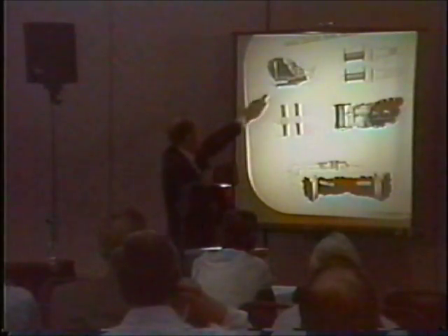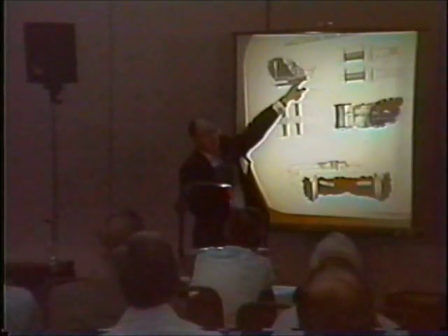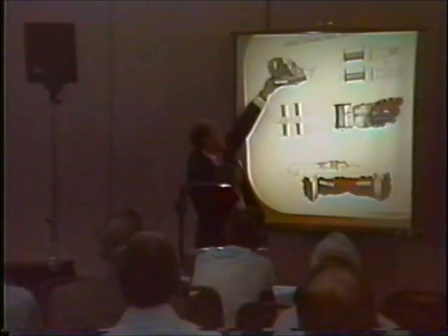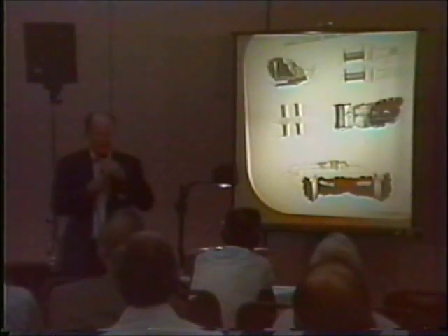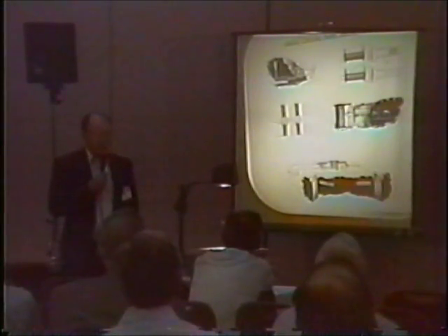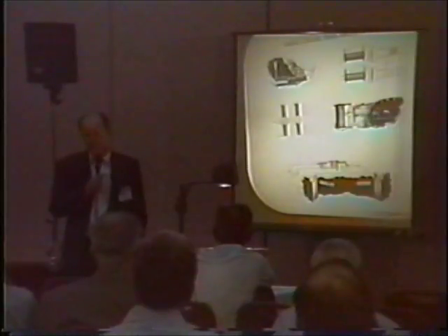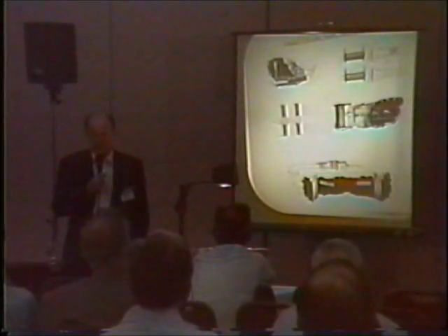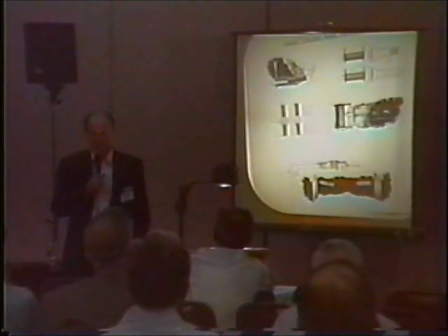You notice on this particular one here, this is your L1 right here, and this is your L2 here, and you're actually tuning this thing by pushing the L1 backwards and forwards in there till it actually matches up with the tuning, and you've eliminated the possibility of having to put capacitors and a number of other things, because the capacitance is already built into the wire that's part of the coils.